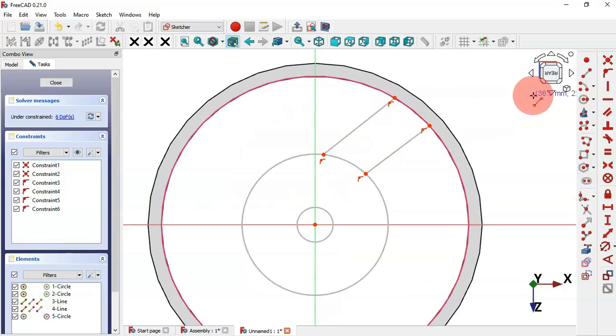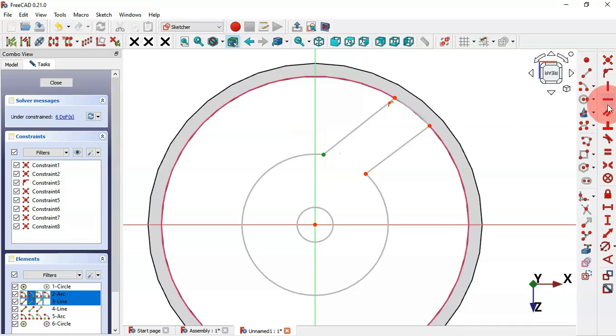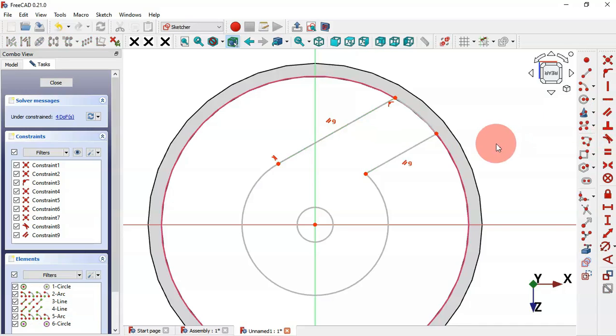Okay, and now select arc tool, click in this origin point and draw this arc here in these 2 points of these lines here, and now select trim tool and let's trim this arc here. Okay, and now escape and select this point here and set tangent. Okay, and now what we'll do is to set these 2 lines here parallel. So first select these 2 lines and set parallel constraint. Okay, and now as you can see, we have 4 degrees of freedom here.